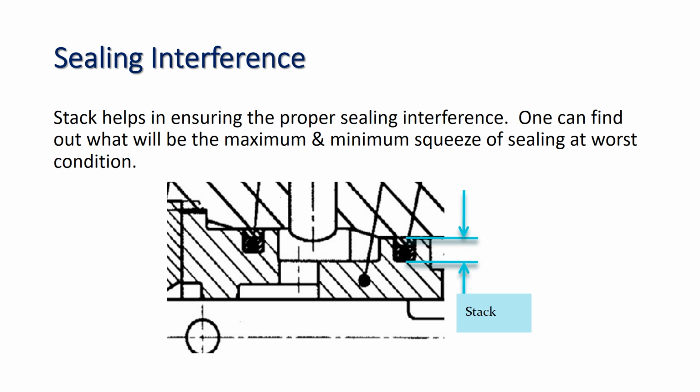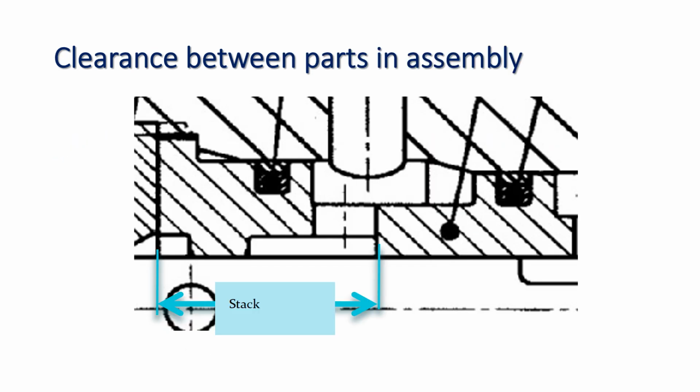Sealing interference: the maximum and minimum squeeze of a seal in worst conditions can be calculated using stack, so that we can ensure proper sealing interference.